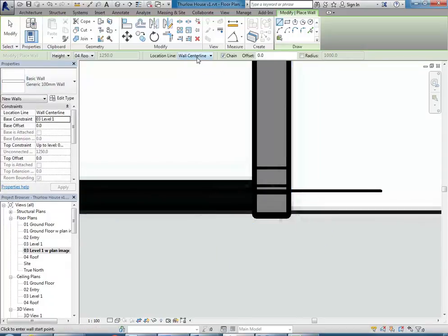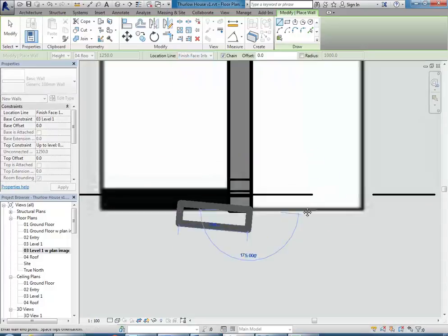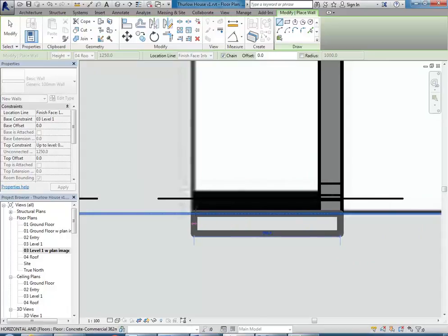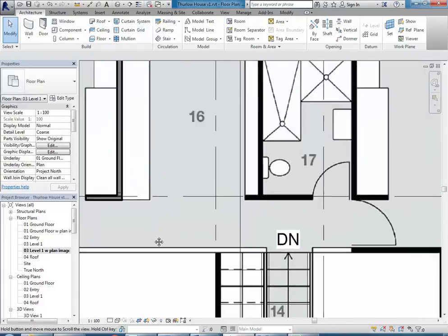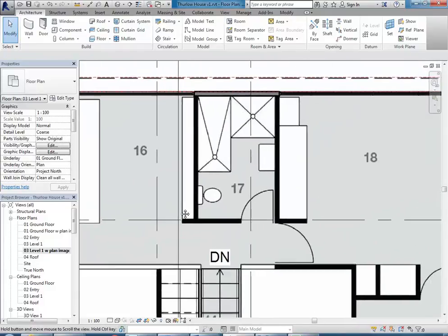So in other words, ignore the doors and windows. Here there aren't too many windows to worry about, but ignore the doors, definitely. And remember, with the internal walls, if they're going to the wrong side, space to flip them, because you usually want to draw them in a certain direction, whether they face the way you want to at first or not.